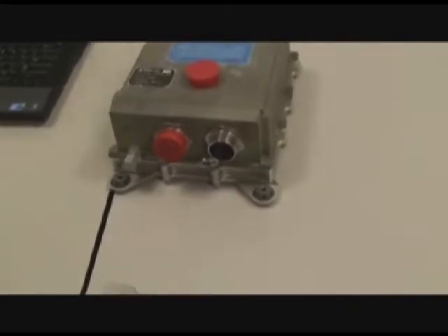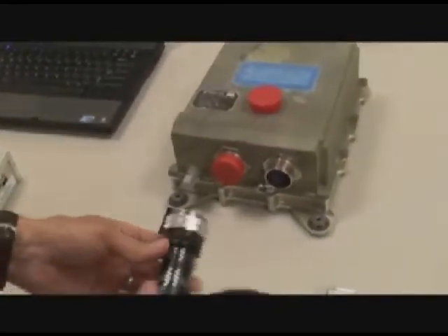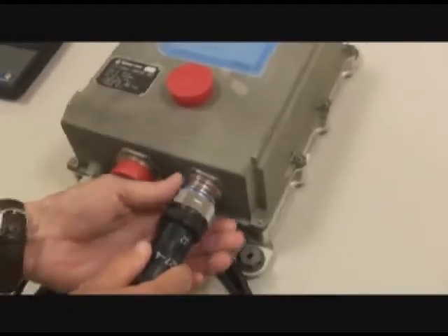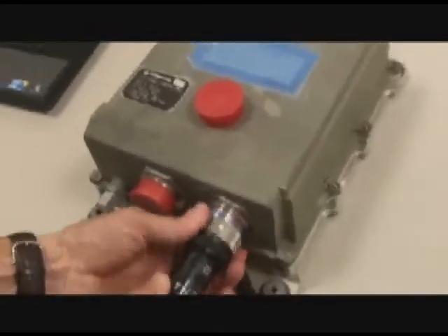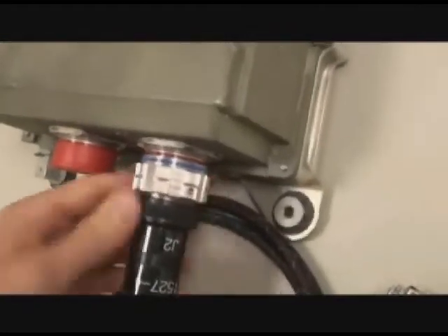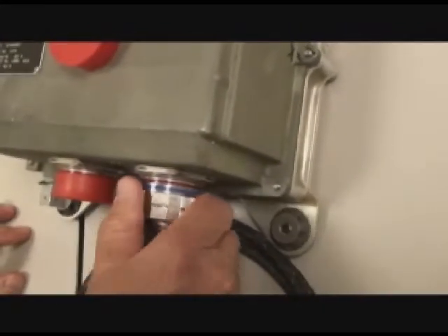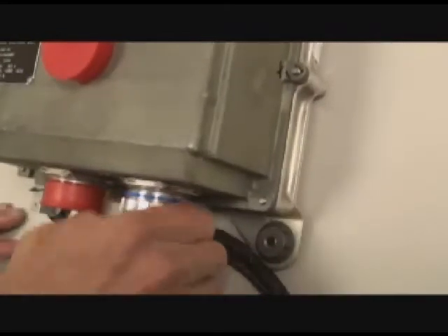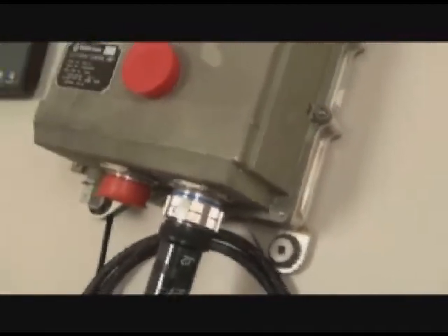Another thing we're showing you is obviously how this procedure works when the ECU is not installed on the aircraft. But this procedure can be done with the ECU installed on the aircraft as well. It's written both ways. So this is installation of the connector onto the ECU. You'll notice that there's a red line on the ECU. You need to make sure that this connector is tightened down all the way such that that red line is covered.